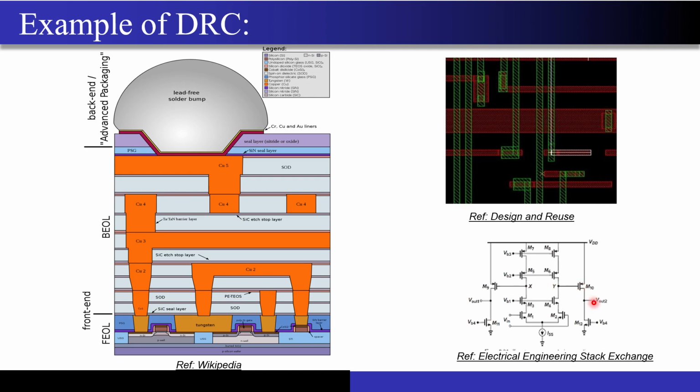And when you do the schematic, you of course have to do the layout, because you just cannot send the schematics to the foundry. It needs this layout diagram, right? After doing the layout, you also send the GDS file, and from that file the foundry actually fabricates your circuit, correct? Now these green color lines that you are seeing over here, let's say these represent a particular metal layer, correct?